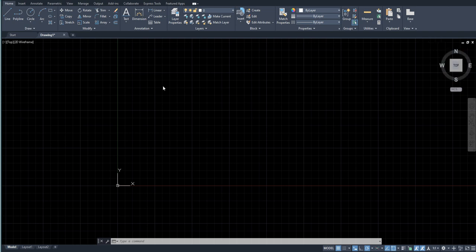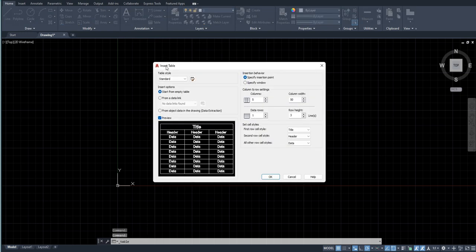So I'm just going to show over here the first option, that is how to insert a table from the Excel file. You can see that you have a small icon over here for tables. You just have to click on this and this insert table bar appears. So if you want to import a table from the Excel file, you just have to have an Excel file.